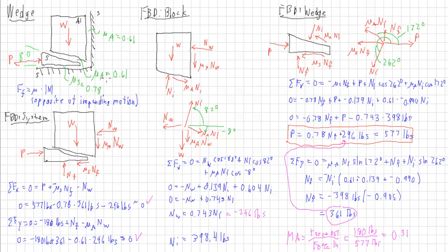Third point is to show the importance of lubrication or other material surfaces. These coefficients of friction are fairly high and could really make it locking, but also make it very difficult to move. So you need to have an appropriate balance of that.